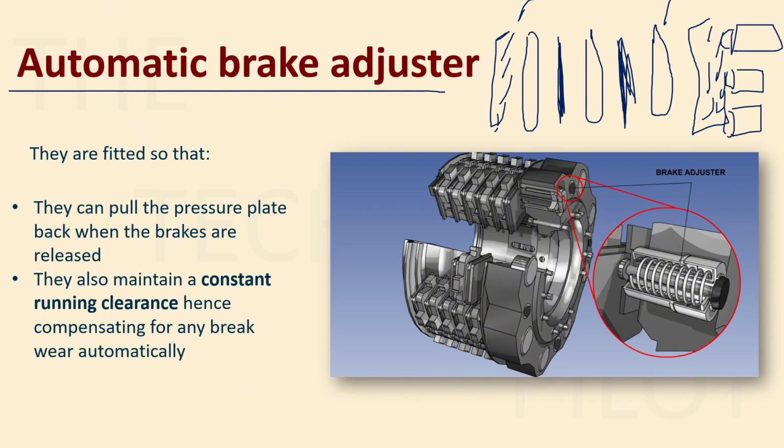So tell me, what will happen if I apply the brakes? The piston will move forward, right? They'll compress this whole thing together, and the rotor plates and the stator plates will come in contact, right? And the brakes will be applied.